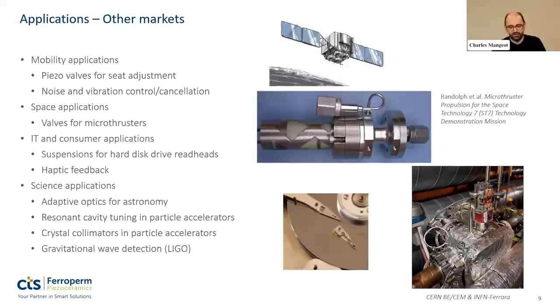Particle accelerators are also users of piezo elements for tuning. Here it's the same idea, but it's a resonant cavity made with a superconductor that needs to be adjusted in length very precisely and very rapidly, because each time there is a beam going through the accelerator, it heats up the cavity, and that creates a thermal expansion, and that needs to be compensated. Otherwise, you're not tuned anymore. So we have a piezo actuator that reacts in the microsecond time frame to correct the dimension.